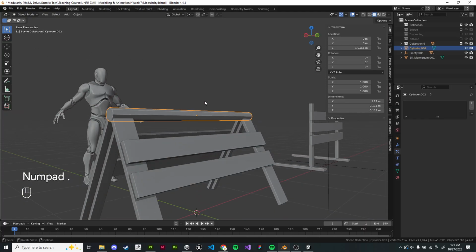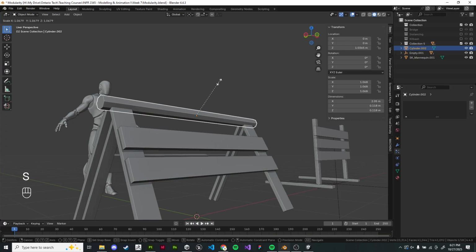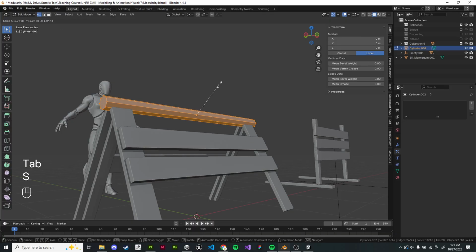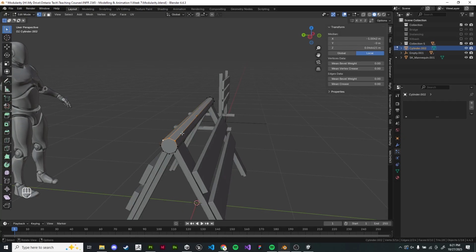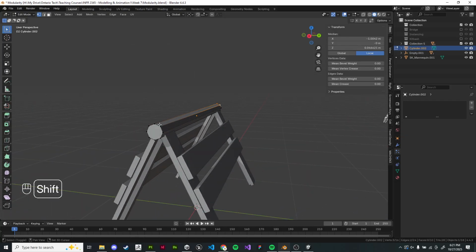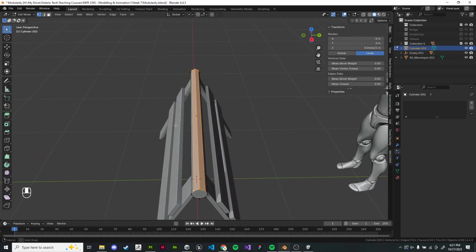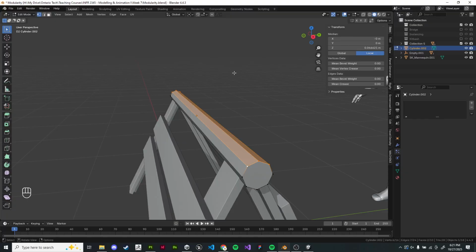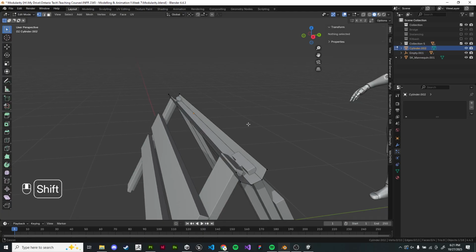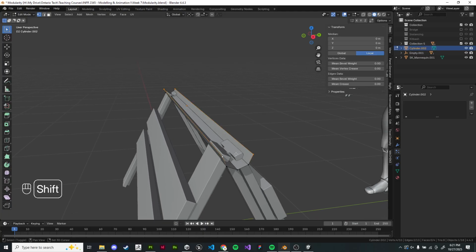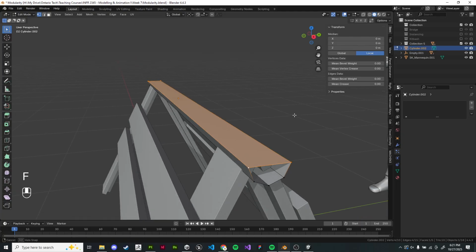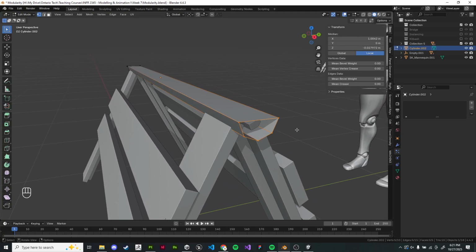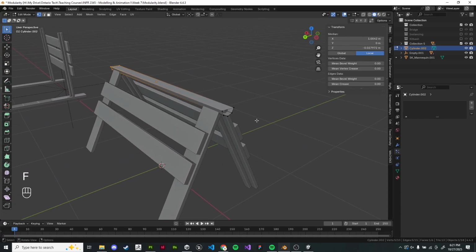So the last thing I'm going to do here for this rectangle is I just want to oversize it a little bit because I think it'll look better. So in edit mode, we'll scale it up. And I want to delete the top. So I'm going to delete those top 2 faces. If that's selected, I can hit X, delete. And then I'll select our now isolated little dots and press F to build a new face. And then I'll select the end and make a new face, and the other end and make a new face.